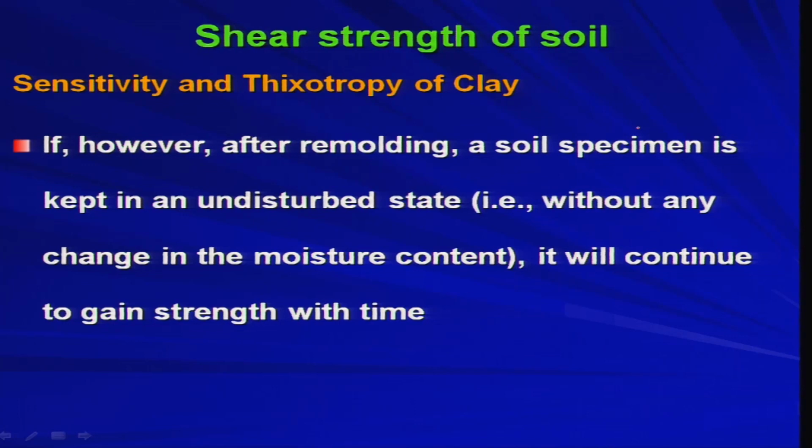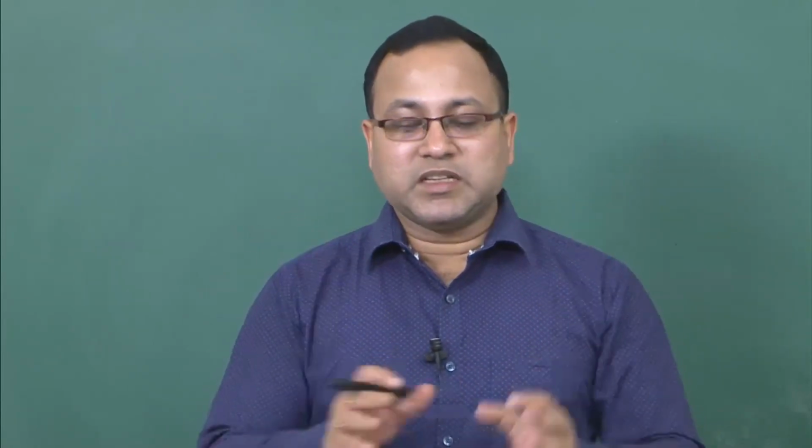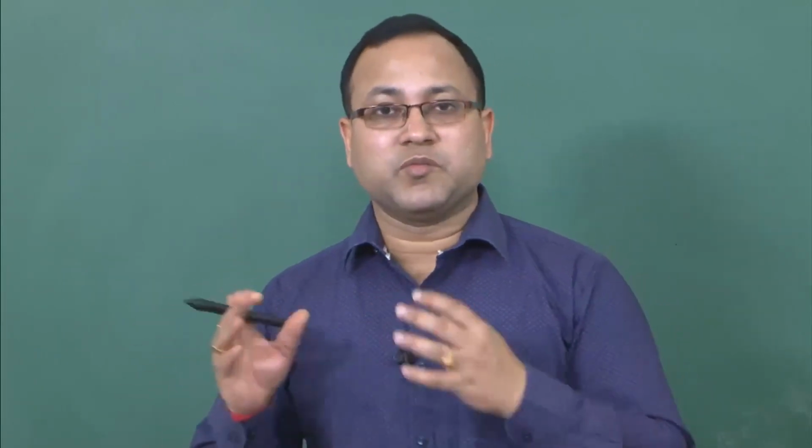If, however, after remolding, a soil specimen is kept in an undisturbed state, that is, without any change in the moisture content, it will continue to gain strength with time. This is a very interesting thing in soil. So what does it say? Undisturbed state means you are not changing the moisture content. You collect the soil sample, which is now a remolded sample, and you take enough care that the moisture is not lost from the soil matrix.